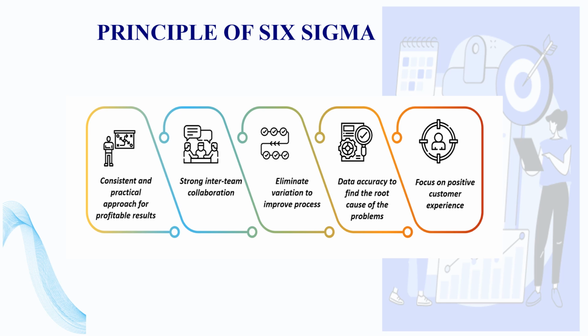Then, the third principle, reduce variation and eliminate defects. The objective of that principle: consistency is key in food production, whether it is the taste, texture, or packaging. Reducing variation by minimizing fluctuation in production parameters, for example temperature, humidity. Six Sigma ensures consistent product quality. For example, a food manufacturer can apply Six Sigma to maintain consistent baking temperature, reducing number of undercooked or overcooked products.